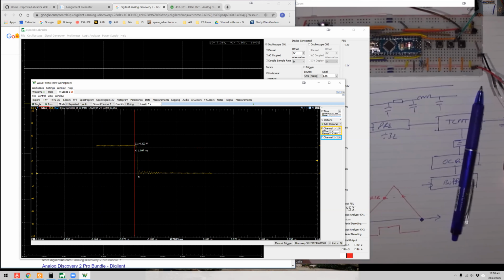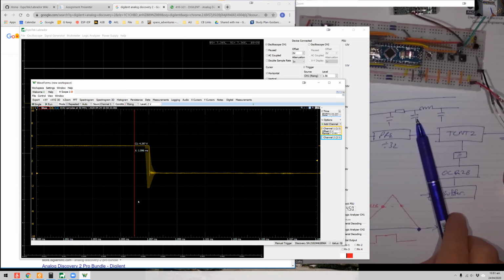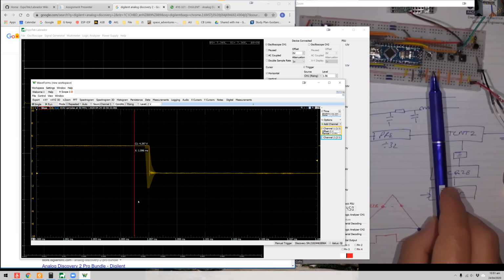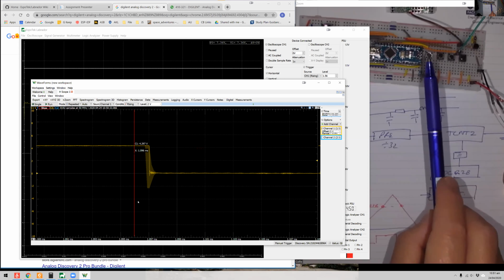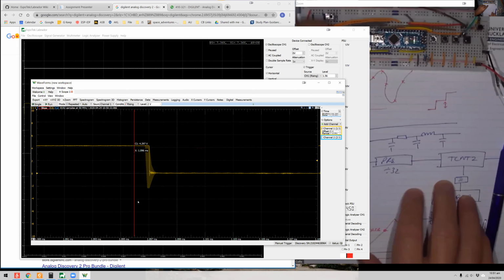So what you're seeing is the ringing. And here you can see the average values that are taking place around this, that it's collected over a short period of time. So this is a better piece of equipment. Just be aware, you get what you pay for when it comes to an oscilloscope. Of course, what's causing this ringing? These inductances and capacitances around this circuit, even these wires. If you want to make a decent measurement, you're going to need a good scope probe and a nice test environment. So I hope that helps you understand a little bit about our sampling rate issues.